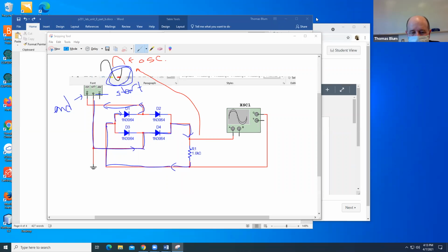And it's usually a simple question of, is there a voltage? And usually there has to be not just a voltage, but enough of a voltage. So is there like 0.6 of a volt in the direction that the arrow allows it to go in, then you would say, yeah, it's conducting. So it won't be this involved. It'll be a simple, here's one diode, is it or is it not conducting?